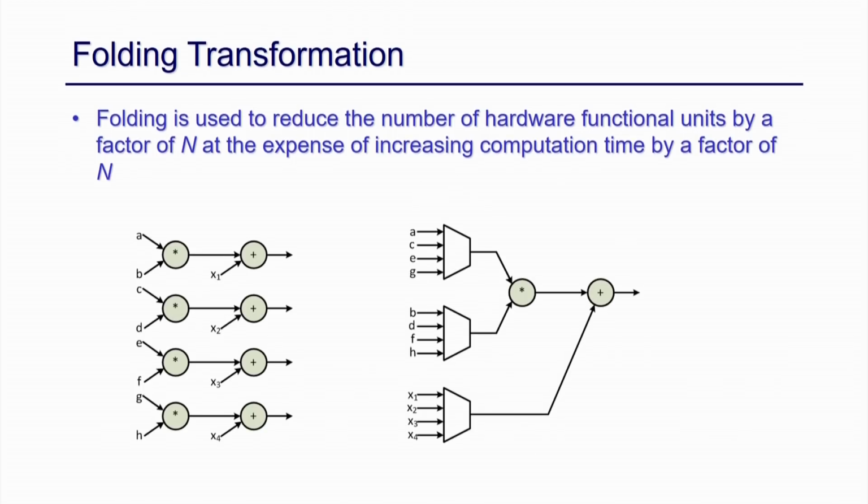Okay. Let us take this example. Suppose I am doing multiply and add, multiply and add in parallel. So, there are 4 such components in your design. I just copy pasted them from a different part of the design. If you think about the hardware, I have 4 multipliers and 4 adders, all running in parallel. So, what we can do is identify this MAC pattern, the multiply and accumulate pattern, and use only one of the pattern in your design.